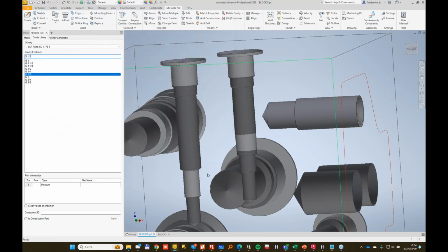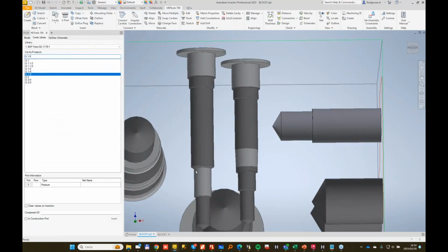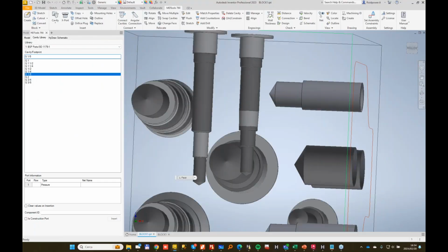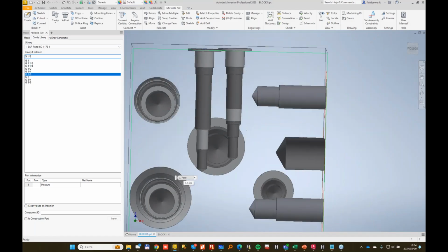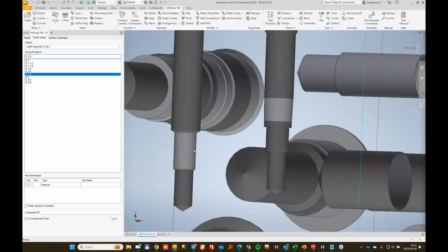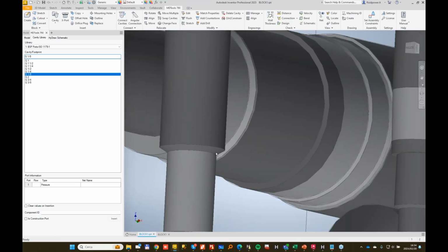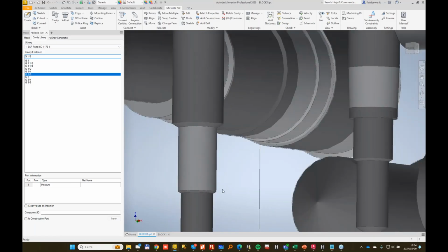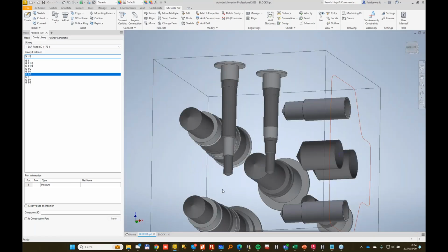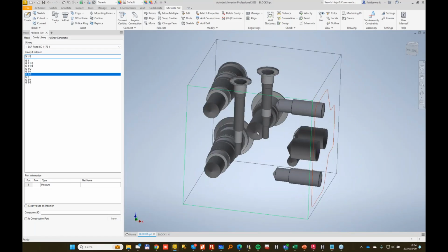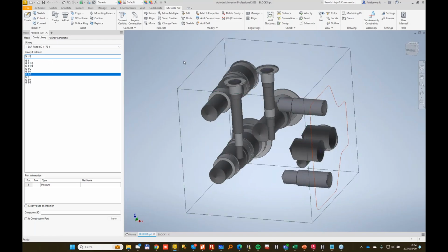And I think I'll use the same technique also for metric orifice plugs, because then I really can control the depth much more easily, because otherwise here the depth is calculated from the intersection between the cone and the starting point, and I really like to have as few decimal places as I want. So this is a technique for orifice plug.